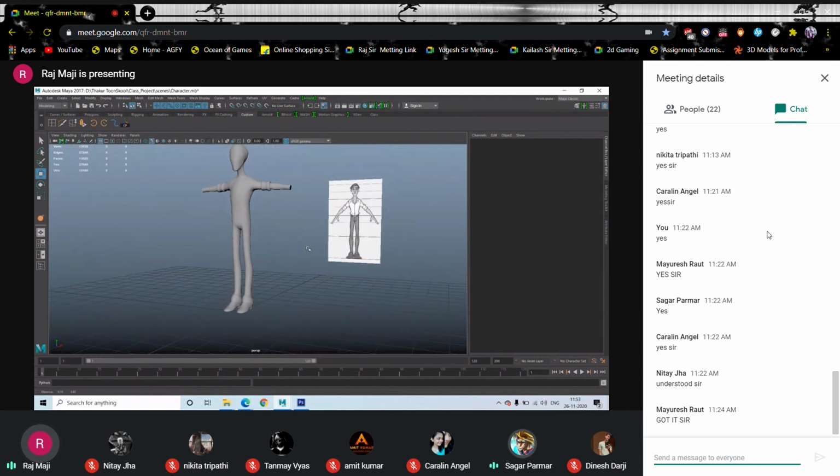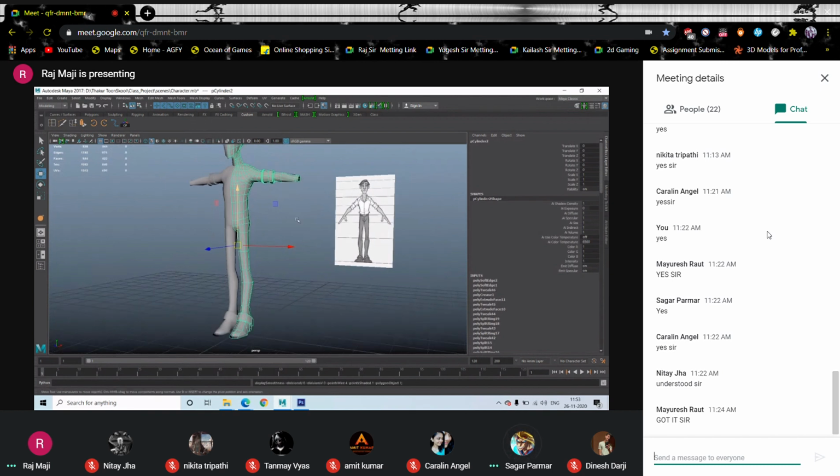Okay. A few adjustments can be done with edge loop. Sorry. That can be done with edge loop also, no? Yeah, crease should be done with edge loop only. Single edge also the crease can be done, but it should be done with edge loops only. Otherwise, you'll get a very different kind of result. Now, for the lips also of the head model, I showed this crease tool, I guess, right? By selecting individual edges, that also can be done.